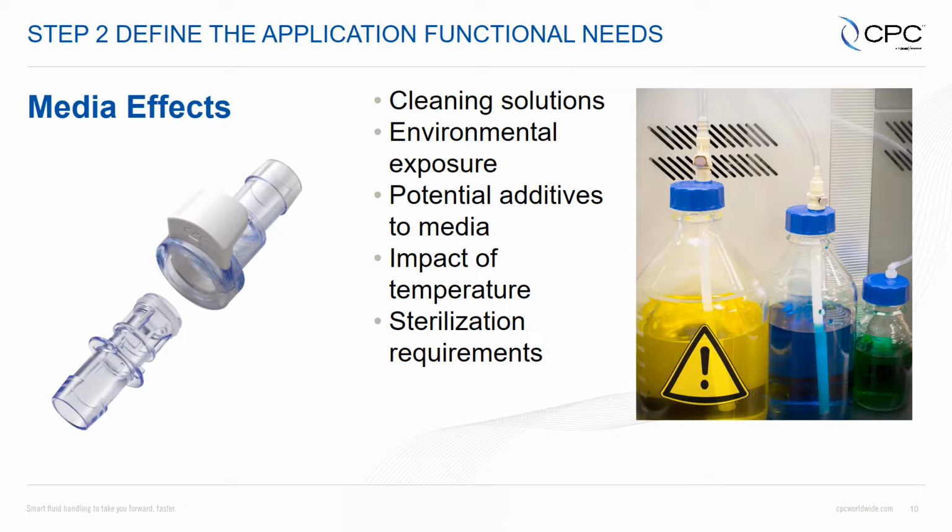The other thing that you need to make sure you're aware of is potential additives. It's very common at CPC for someone to contact us and say, we're using this media and it should work, but we're having chemical compatibility issues. When we dig in with them, we start to investigate and analyze the fluid, there might be something in there to prevent freezing, or to prevent mold or mildew, or some sort of fungicide inside this media that they weren't aware of, and it's actually those additives that can create a chemical compatibility issue.